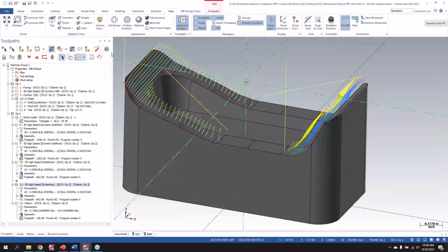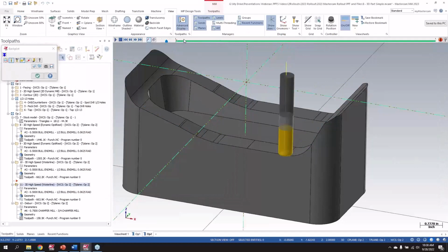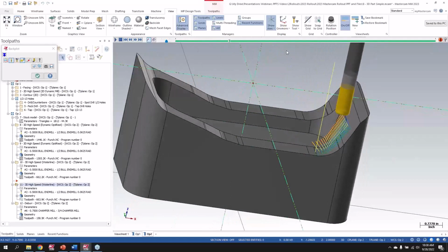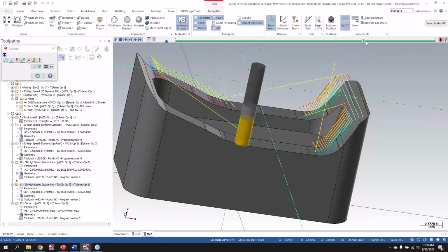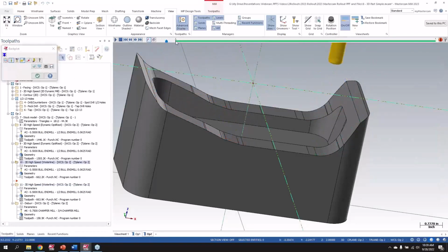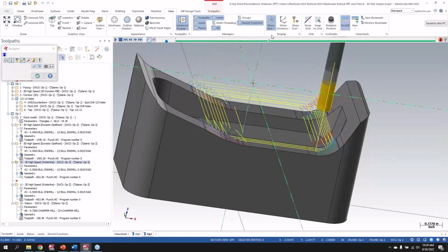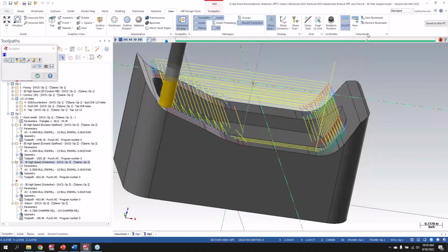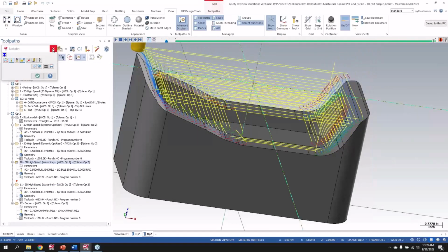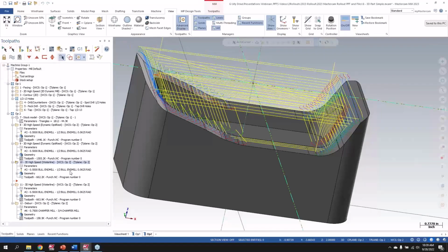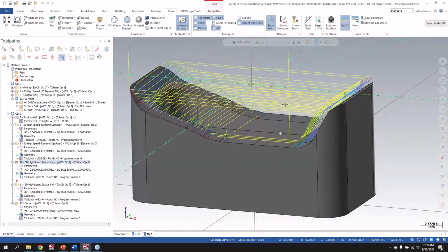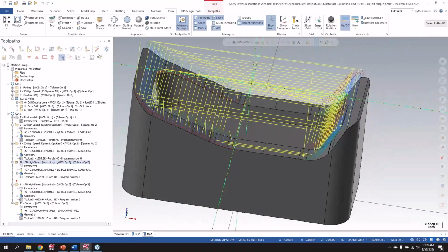And then I get a much cleaner waterline toolpath where it's going to do section by section, walk up that wall, do the top part, then cut across and do the other side. Whereas the previous one was very inefficient, since it was going by depth, it was doing each depth cut, and I have 10x the amount of retract, reposition moves as opposed to using that optimize command. So just another handy little update to refine these toolpaths a little bit.